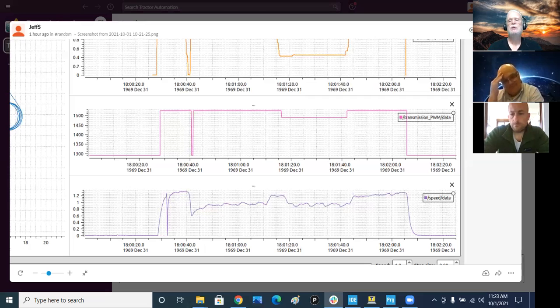So what I'm suggesting is that at the lowest level, you do this ramp up and ramp down, and then plot out the results, and that'll tell you if the transmission is following the PWM you're putting into it. Because it might come up like this and then ramp off instead of tracking while the other one's still going up. That might be a worthy experiment.